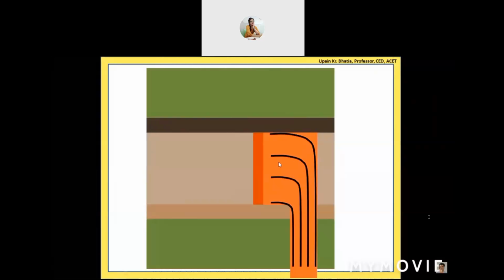They are low height, very thin walls, and the top level of these walls is a little above the canal bed level. What you see is that here the gap between the walls is very high, and here the gap between these walls is low. We can provide intermediate walls also, which may not run up to this end, but are provided in intermediate positions and run up to these points only, here, here, and here. The water going through will ultimately merge here, so they are provided in this fashion.